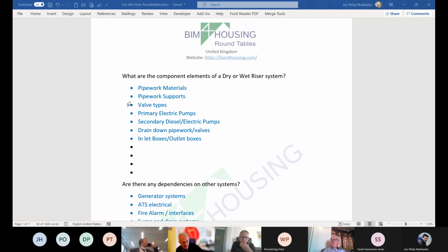Basically, they have a nozzle on the wall, and the standard assumes the nozzle is on the ceiling, out of the way. But yeah, it's something to be careful of with water mist, and it's indicative of the government's guidance in Approved Document B that it doesn't offer water mist as an alternative for flats higher than 11 meters. It does say sprinklers, and that is not an accident. The same approach has been taken with BS 9991. So water mist isn't a bad thing, but there's been some unscrupulous people in that business, and it's rather trashed the reputation of it, I'm afraid.